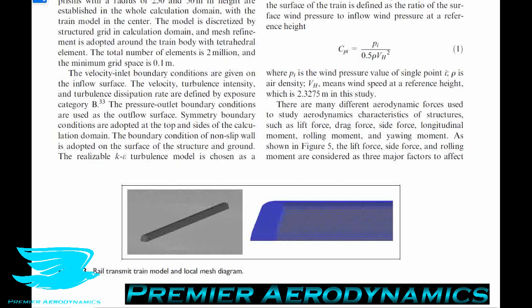So the boundary layer should be thicker than what it will be in reality, unless I'm reading their setup incorrectly, but I don't think I am. So that means that this non-slip boundary condition for the ground is not that accurate. In reality, you could either correct for this by making the ground a moving ground condition, or by altering the coefficients in the turbulence model, the former way being much easier than the latter way.